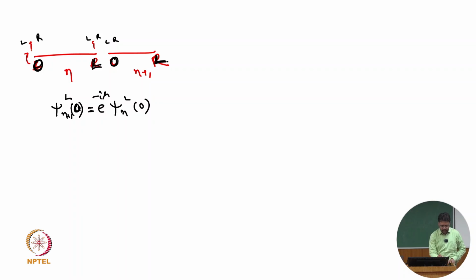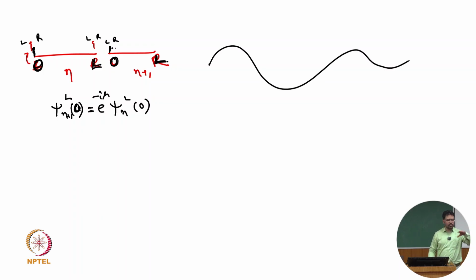So whatever is the displacement here and whatever the displacement here, if we remember that Bloch type thing, we are assuming that a single wave is going in that space, so they are correlated. Displacement, bending moment, shear force, all are actually vectors. So these all vectors can follow that Bloch theorem. So they are getting correlated. Next thing, we have also seen phi n r.